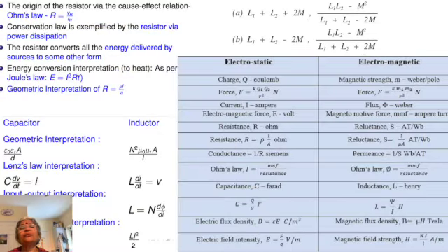And when you're talking about a pair of inductors, which is a very important application with respect to machines, then two aspects come into the picture. Of course, the pair also produces what is called a mutual inductance between them, and so the nature of the flux also becomes important. There are two possibilities. One is that the two fluxes created by the two coils may be aiding each other, or they may be opposing each other. The next feature to be considered is whether these coils are connected in series or in parallel.